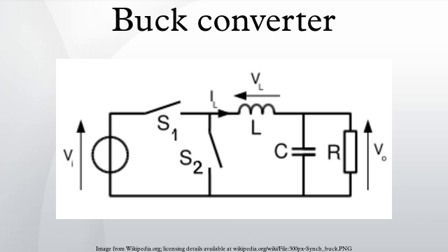Current can be measured losslessly by sensing the voltage across the inductor or the lower switch. This technique is considered lossless because it relies on resistive losses inherent in the buck converter topology. Another technique is to insert a small resistor in the circuit and measure the voltage across it. This approach is more accurate and adjustable, but incurs several costs: space, efficiency and money.